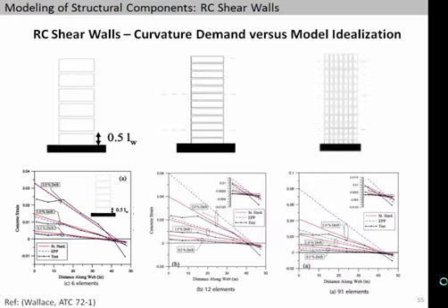In finite element models, we sometimes hear, well, you refine your model and you're going to get a more exact answer. But in this case, when you go to a more detailed model, you tend to get very localized measurements of strain, which then become far apart from what they are in the test. So this is where the so-called art of analysis and engineering comes in. And I think Graham Powell, who's worked a lot on modeling walls, really will advocate, for the gauge length, if you will, or for the size of these elements, to pick them as a story height or half of the wall or pier dimension, not to go finer than that to avoid these sort of problems.